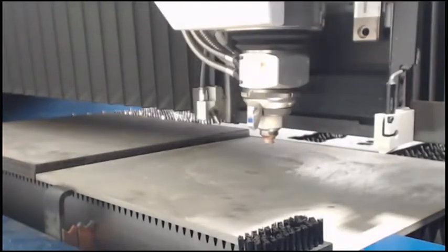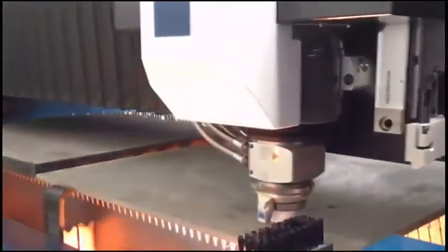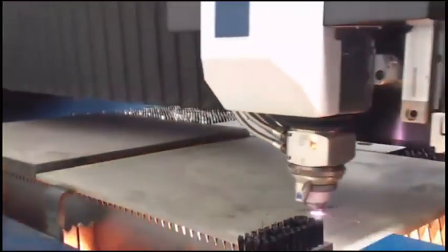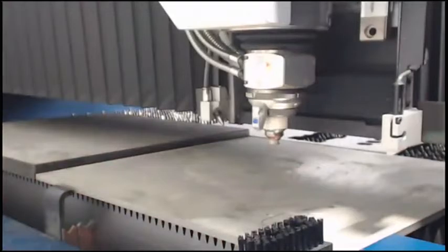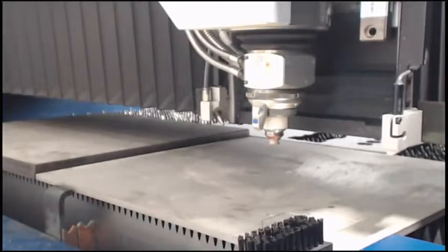It actively looks at the beam center. It actively looks at the cut to ensure that it's a good quality cut. There you go. You can see that it pierces really, really quickly. Again, 267 inches per minute on that 3/8 stainless. And again, that's with nitrogen. Pull this out and show it to you guys.